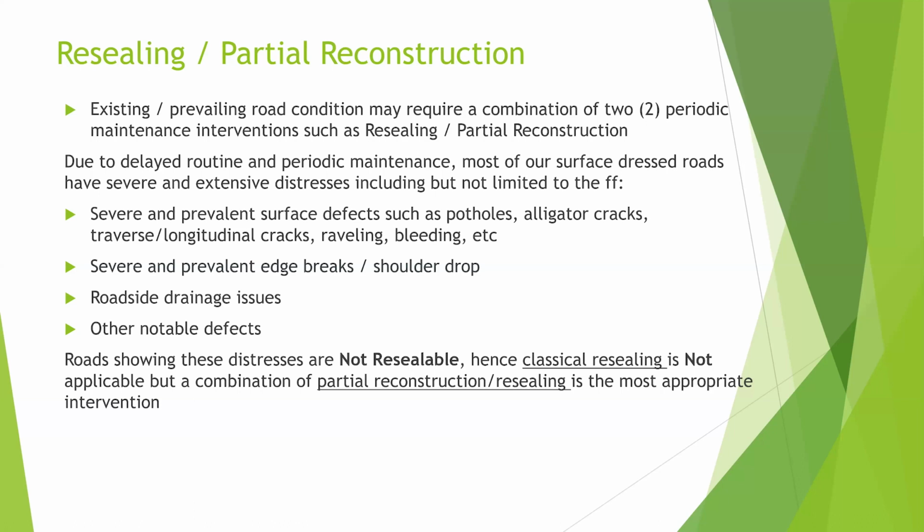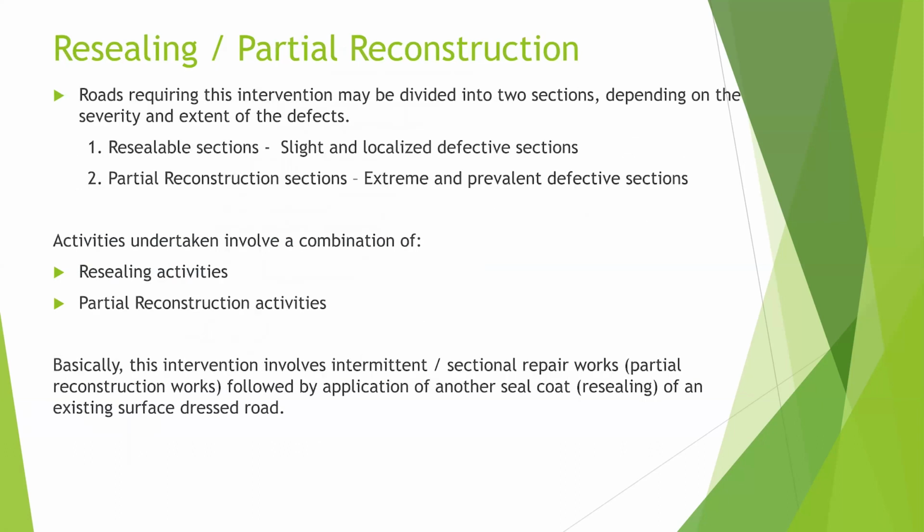And so when you have those and the roads are not purely resealable, then you would have a combination of these two. You undertake both the resealing and the partial reconstruction. In this case, sections of the road are resealed and sections of the road are partially reconstructed. Yeah, so that is what I talked about.